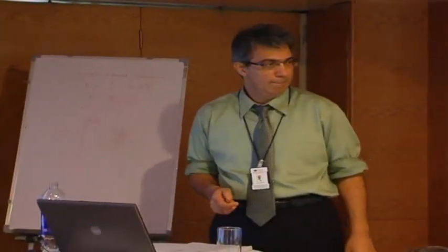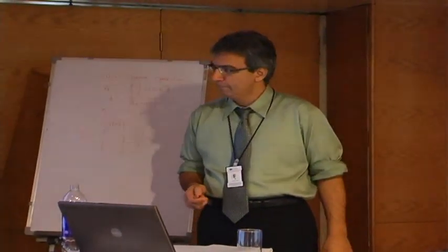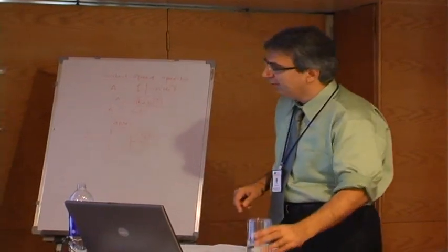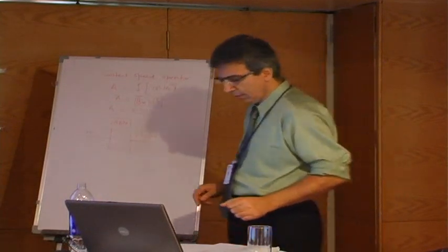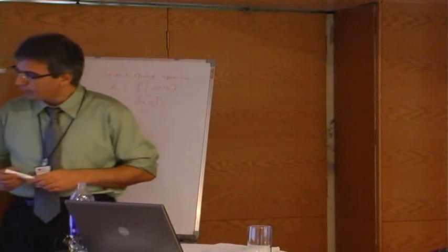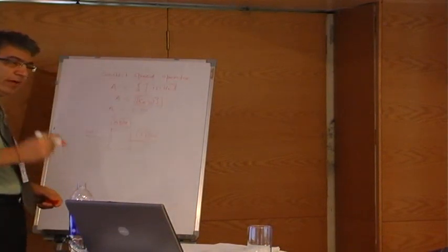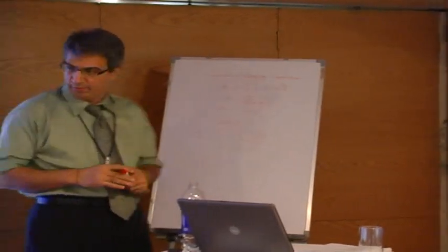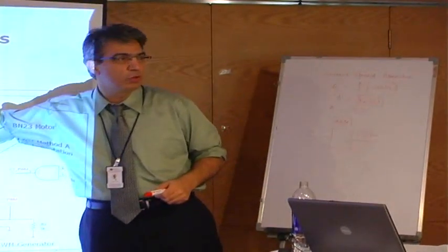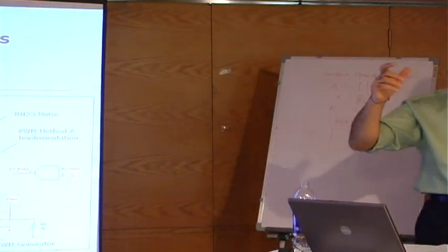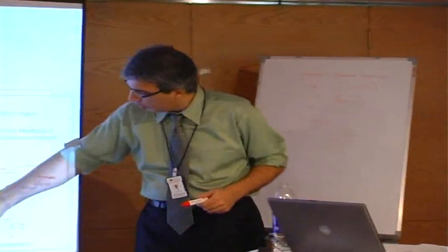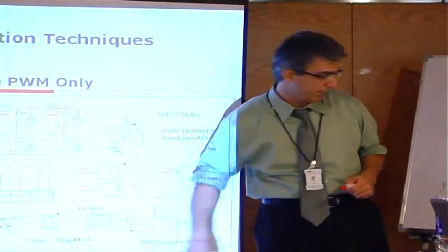Is it a duty cycle limiter? Yes. But how is it going to help with the shoot-through? Good question. Let's see. If I have a complementary drive, and let's say a dead time between the two, if I take an IR driver, an International Rectifier driver, I can have a dead time of about 500 nanoseconds. So if I have a MOSFET and I'm going to, let's say, 0.99, right?